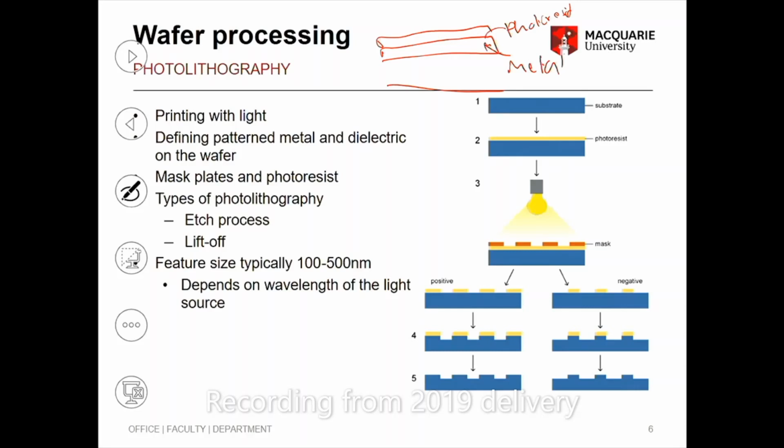So when you have photoresist, then you put a mask. If your tracks are there, let's say this mask will cover this area. Then you light up the surface, and these things get scratched away. So you are left with the metal and the photoresist mask covered, right? Then you can wash away the photoresist, and you have the metal. So this can be your track. That's called positive. So you can build up a lot of layers.